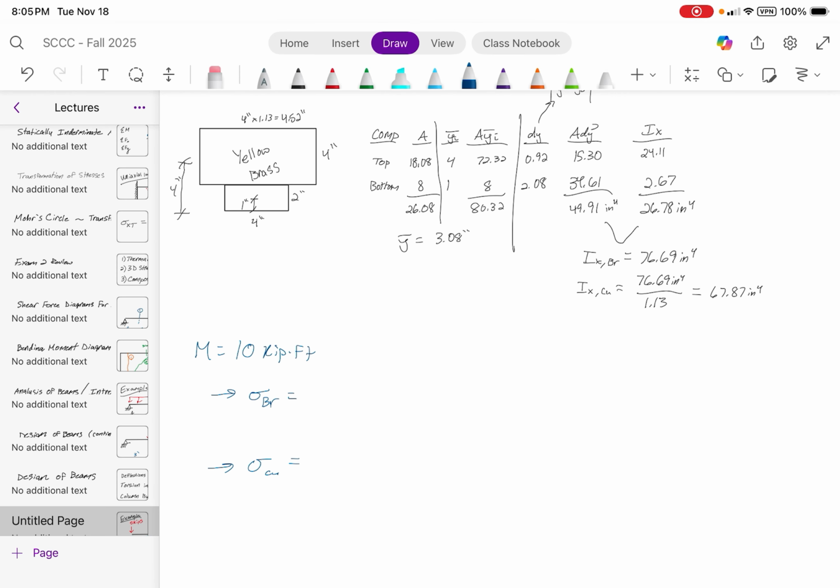For example, these are all openings around stairway openings. This is an elevator shaft right here. This is a ventilation shaft, I believe, or staircase, I forget what exactly it is. But you've got a ton of reinforcement. This over here in the hatching is actually a slurry wall. They constructed this entire thing, and then they excavated this entire circular area. And this slab here is just one of about 4 levels of slab.